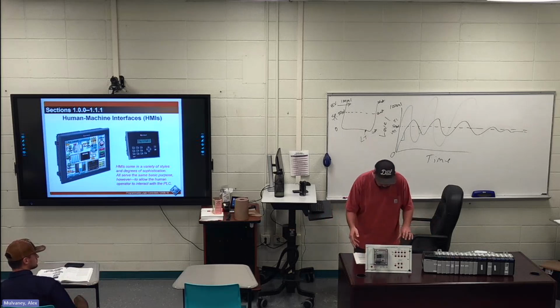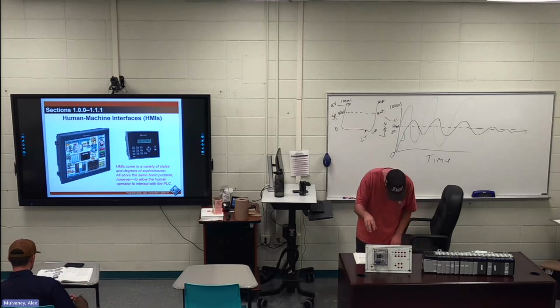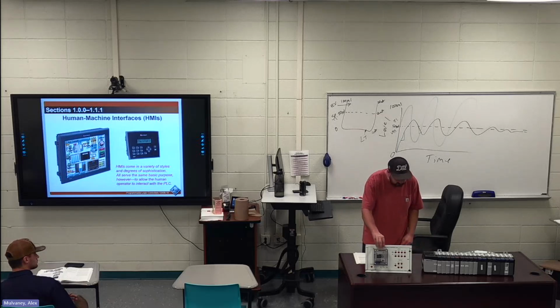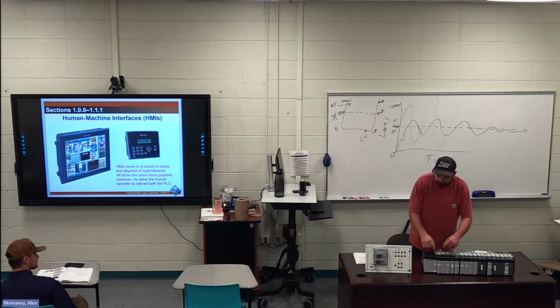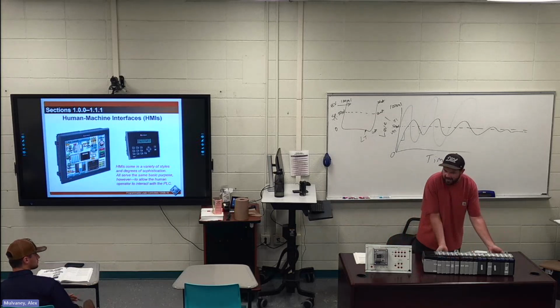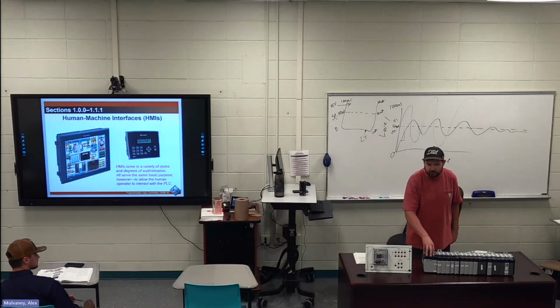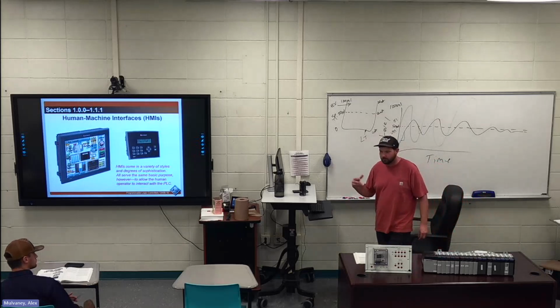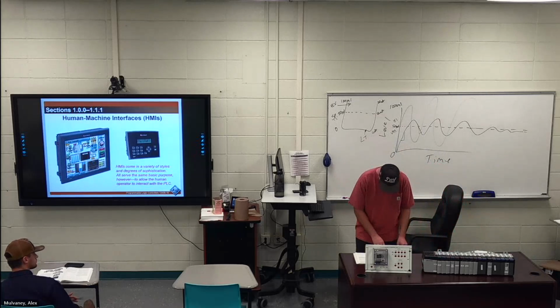Also, it says primary hardwired component. Yeah, it's just this or that. When it says modules, I've talked about this before, but it's each one of these different things. And then this rack has a back plane. This is the power supply. Then it would have a processor and stuff like that. That's the actual hardware of the PLC.